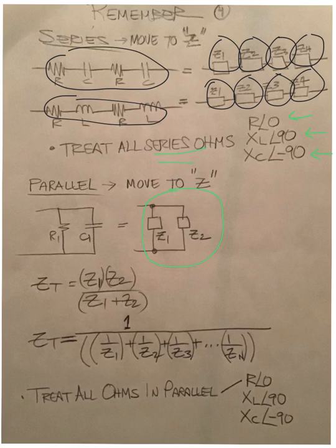But if you're in parallel and you only have two impedances next to each other to form that parallel circuit, which happens a lot, then you just need to use the product over sum, or in some instances, if you have 3 or more impedances, you need to use the big dog formula.